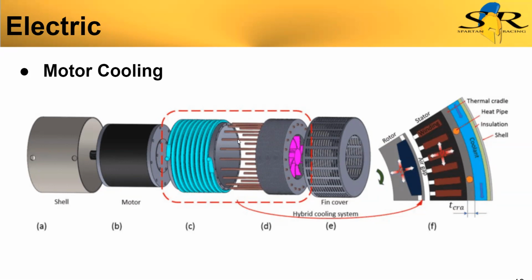They transfer the heat really fast, and they work well in electric systems and motors because the geometries are a little more simple, versus a combustion engine where the motor is likely cast, and there are all kinds of odd shapes and galleys and passageways and channels that aren't conducive to heat pipes.